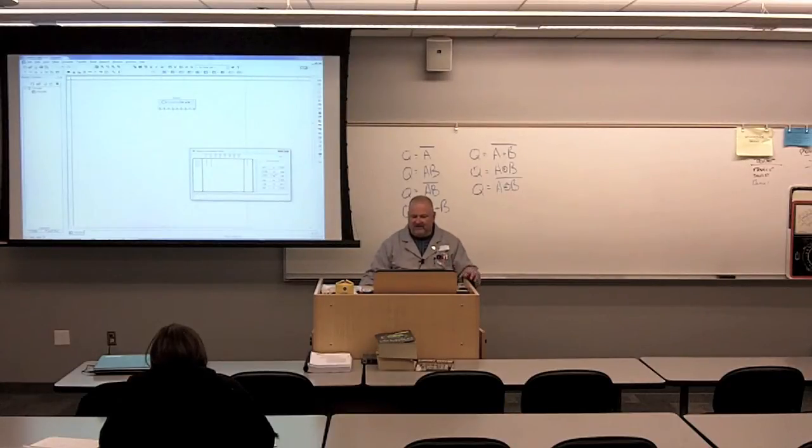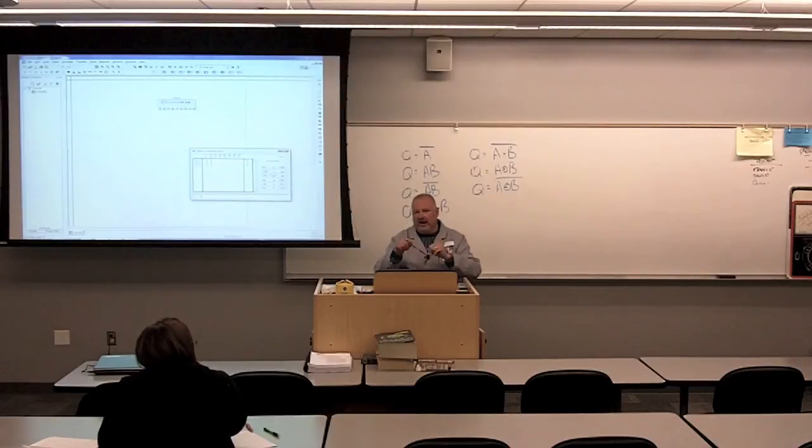Okay? So I've put my cursor now in that Boolean box in the logic converter. Now I'm ready to go. Okay, so the way we would say that, A and B not. So the B has a not after it. So the A and the B are not ANDed together.